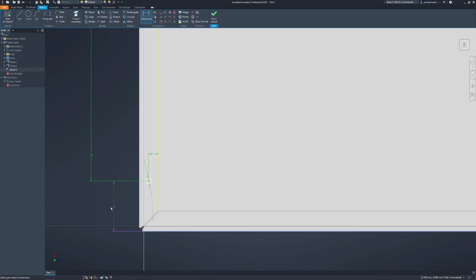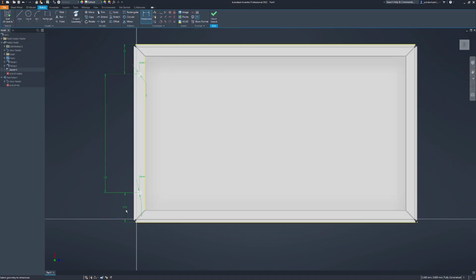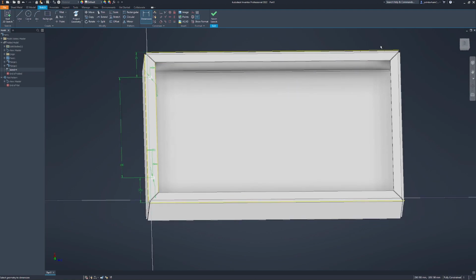This is going to create a driven dimension here because it's already set. So when you see something in brackets in Inventor, it's a driven dimension because it's set from there and it's set from there. So it could not possibly set its own dimension. It's informed by the others. So we set 25, 25, 5, 5. So it's going to be equal. If I create another dimension here, it's going to show up as a driven dimension. There we are. Same thing again. 5 in brackets.